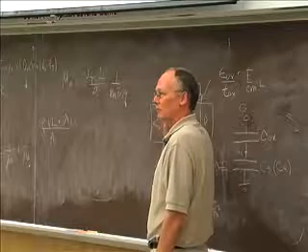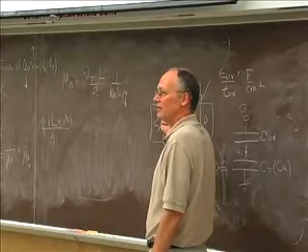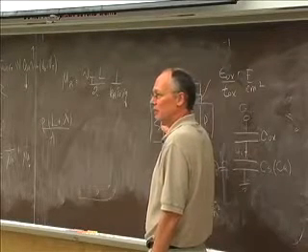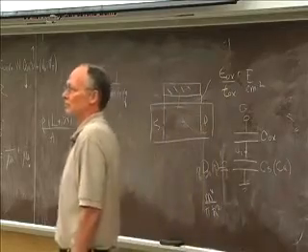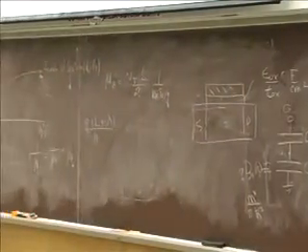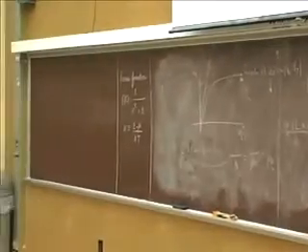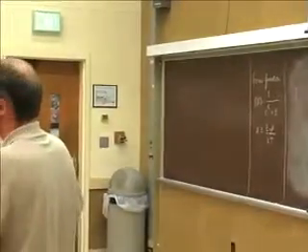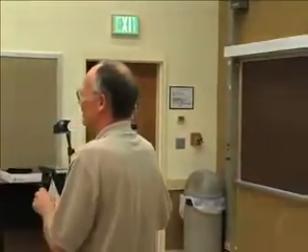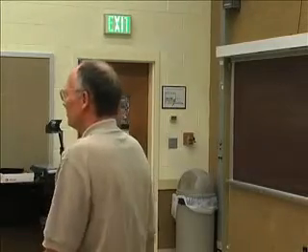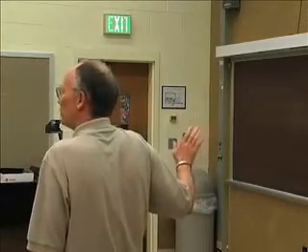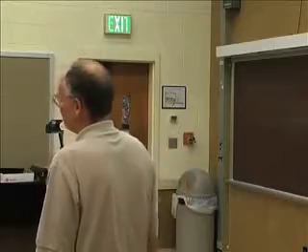Here, right? We're assuming we know the density of states at the beginning of the channel. Is that right? Yeah. Then there are questions. If you get into really small devices, is the effective mass in this very short channel device in that region the same as it is in the bulk silicon? To first order, it's pretty good to remarkably small devices.